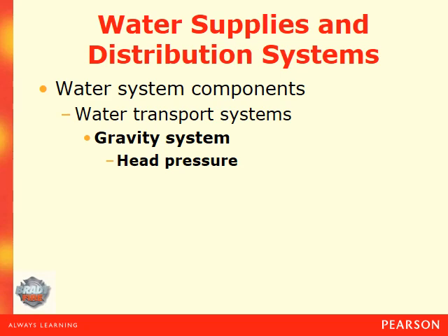So the water comes from either elevated towers or from a pumping station high above the town. And then the water leaving that object or system develops something known as head pressure, and that is the amount of pressure that the water produces from going downhill by means of gravity. This is used to pressurize the system, which allows the water to get transported from its starting point to the end user or where your faucet is.